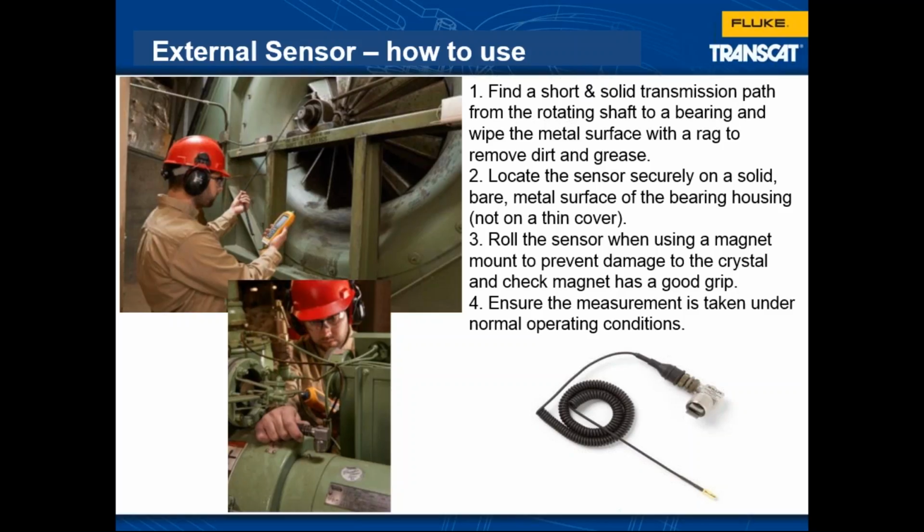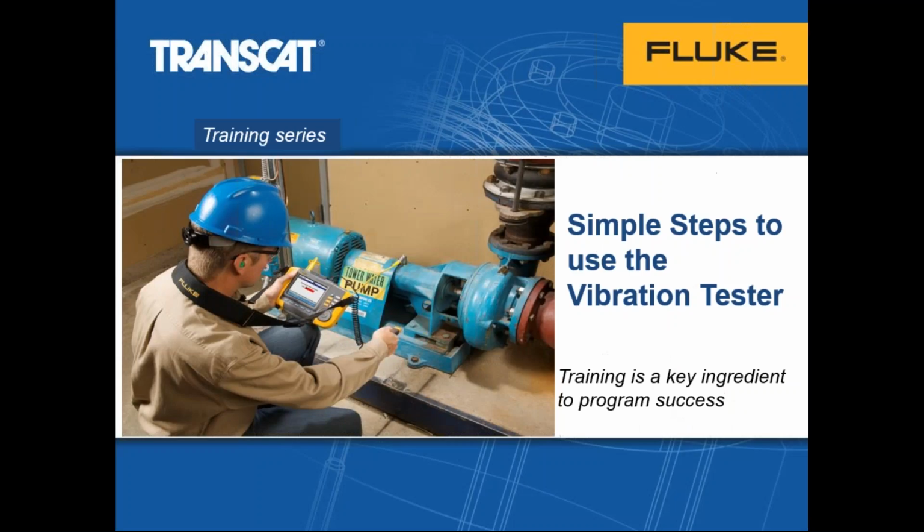Okay, so we went through the vibration meter, and remember, the vibration meter is simply going to tell you, is the machine good or bad? After you find out the machine is bad, now you need to call in a vibration tester, the doctor, to tell us what the fault is and what to do to fix it. So let's walk through the vibration tester.